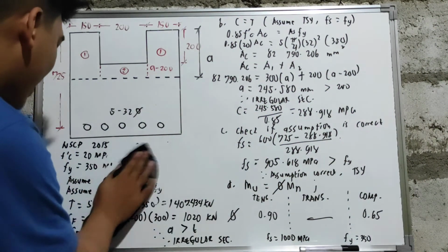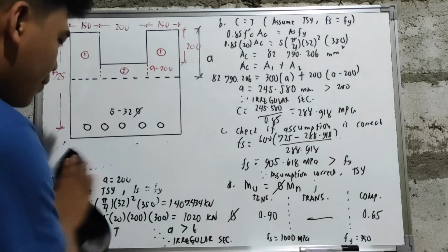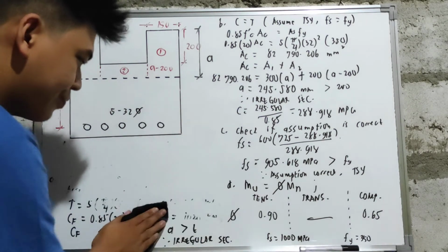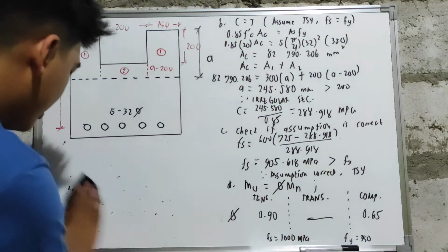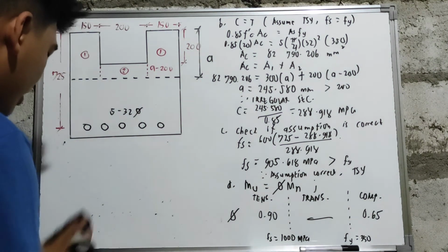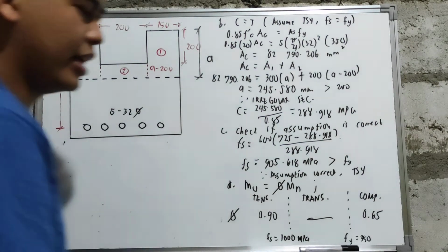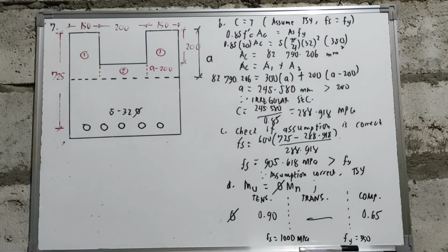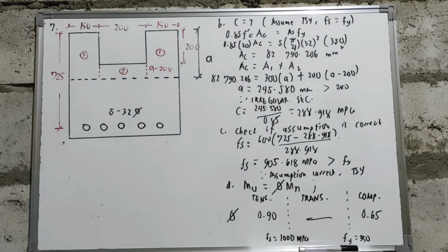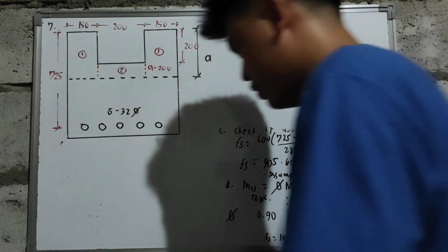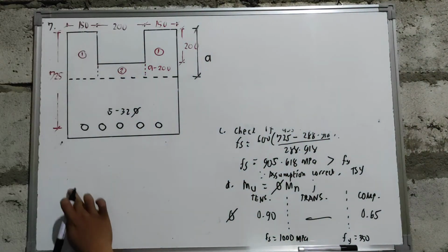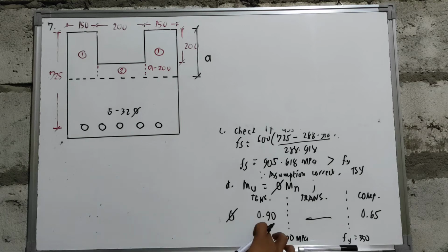Pero I advise na wag na natin gamitin yung mga formulas na yon kasi baka mahirapan tayo sa board exam at saka ma-occupy yung space natin. Ang dami kasing formula na i-memorize pa. So let's now calculate for your reduction factor using linear interpolation. So una, sa linear interpolation, lagi naman ang upper limit muna. So gawin nating upper limit, etong 0.90 natin.